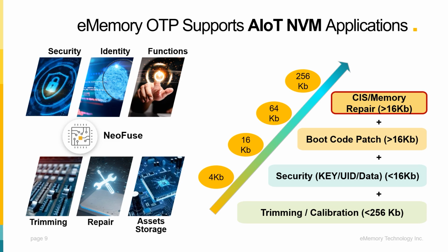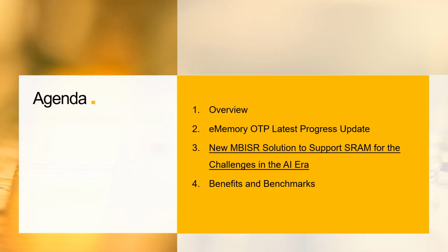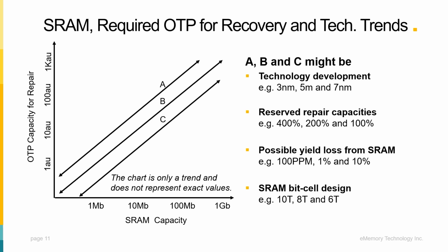In the next section, I will provide a detailed introduction to the solution we have proposed. Let me briefly discuss the current trends in SRAM repair. As SRAM technology develops, the static noise margin decreases due to the scaling down of process technology, the power supply VDD, or the demands of low-power applications for edge devices.